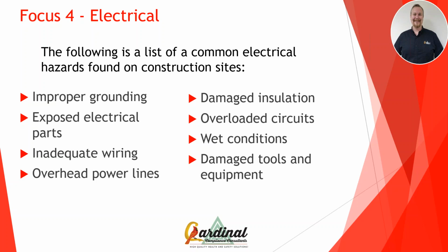Now, improper grounding, and there are a lot of definitions of improper grounding. What I want to focus on is tool usage. There are two types of power tools that you're going to find: some that are grounded and some that are double insulated. Now, when you're working with a tool that has a ground prong, here's the way that works. Electricity at low voltage is looking for the path of least resistance. So let's say your tool has a short in it and it comes in contact with the casing of the tool where you're holding. So electricity has two places it can go.